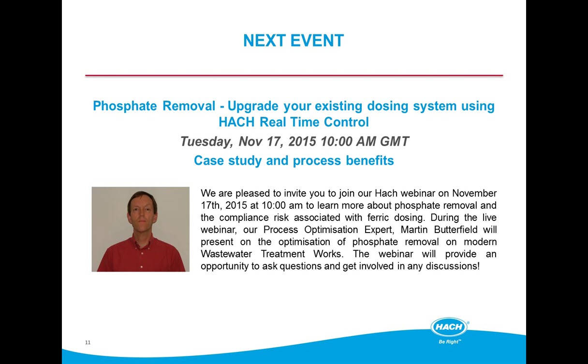But again, this is not a quick thing, and it takes us back to the point where you're spending a lot of time doing an autopsy on a failure rather than having the information up front and being able to make the correct decisions for the activated sludge plant before it becomes a problem. There are methods to try and establish the root cause of an ammonia peak, but without good quality data, there is always going to be an element of uncertainty around whatever your findings are.